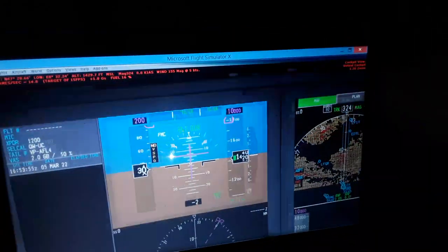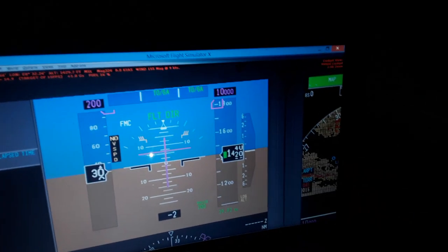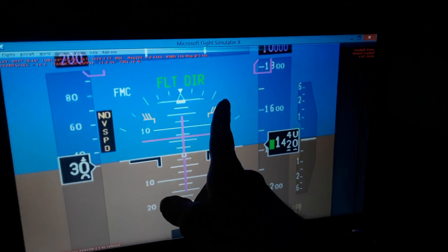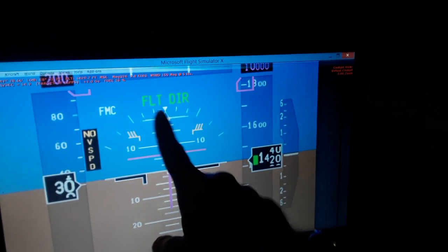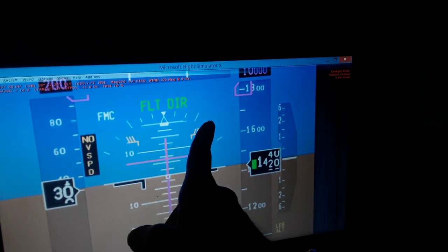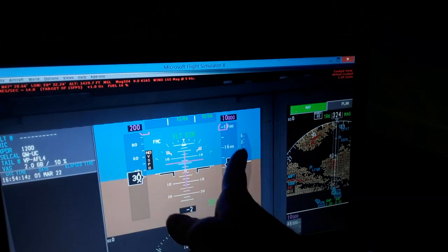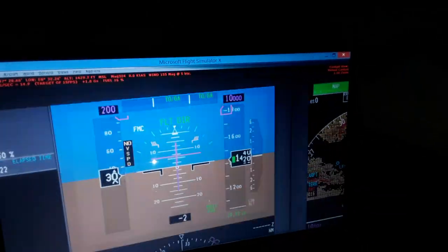Also the flight mode annunciator, you see the autopilot modes and the auto throttle when we arm them. So you can see also the bank roll. Here is the bank roll of the aircraft when we make turns. So you can see like 5 to 10, 20, 30, 45, 60 degrees of bank roll like this. Also the wings level over here of the aircraft.